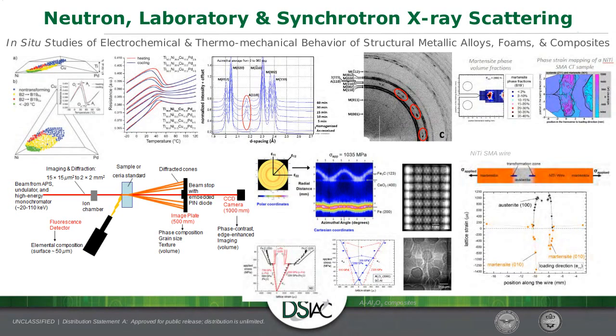So that's where I mentioned earlier, you may want to start with pre-alloyed powders so that you have a fixed composition rather than just relying on nickel powder and titanium powder sort of shooting in and mixing. And so that was the reason for us developing a technique for making shape memory alloy powders. Let me see. I think that's one of the big challenges with them.